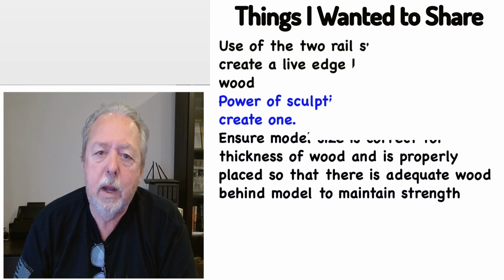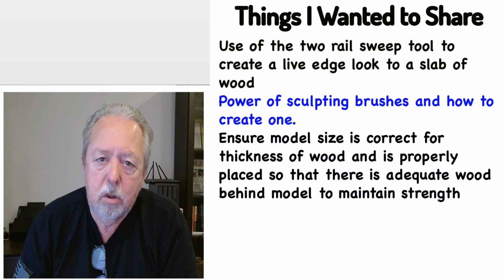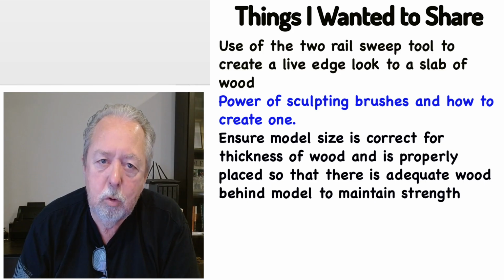Another important factor is to make sure that your model fits within the material thickness that you're using, in this case 1.25. Check before you set up your toolpaths, or once you set up your toolpaths, go to the set button and make sure that the model is sitting high enough that you're going to have some backing.